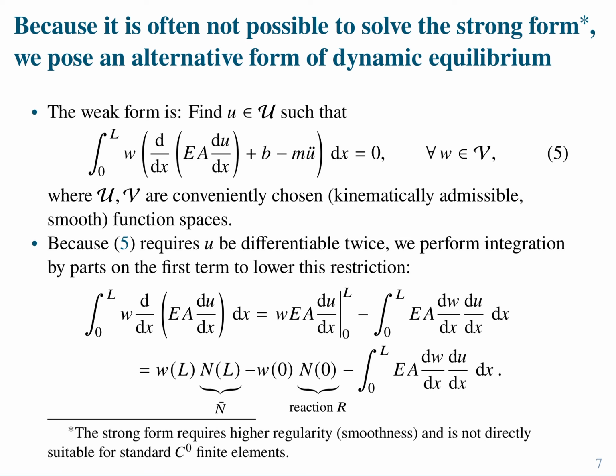Now, there is a little subtlety there, because you can actually prove that the strong form and the weak form are equivalent statements of dynamic equilibrium, equivalent in the sense that you can go back and forth between the two. Because with the variational form, we're still living in an infinite dimensional space. So this is very abstract. I'm getting a little bit crazy here, right? We are living in infinite dimensional space. That means that even with this formulation, you are still able to pick the exact solution of the problem. So that is why there is an equivalence between these two problems.